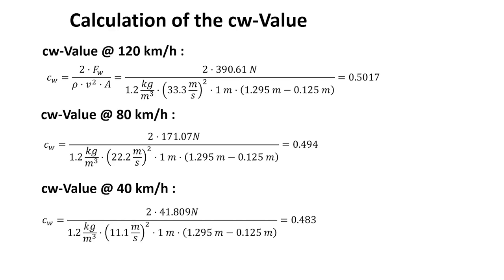For the forces, I had to let the simulation run 3 times, so with 3 different speeds. The version that's implemented in FreeCAD currently does not allow a simulation of a ramp. There are versions of OpenFOAM which allow this, but according to my information, it's not implemented. So you have to calculate this 3 times to get 3 values.